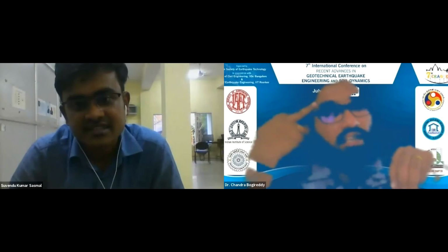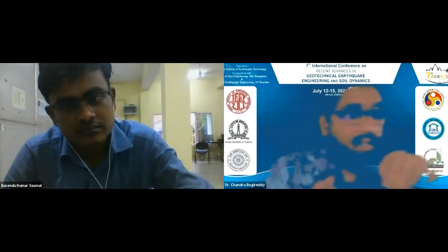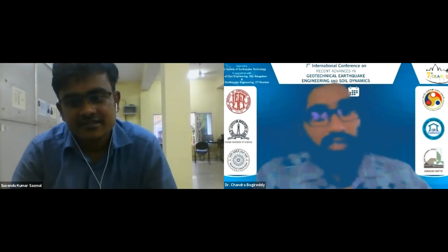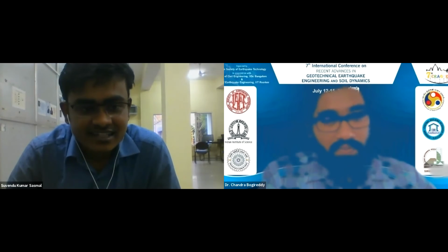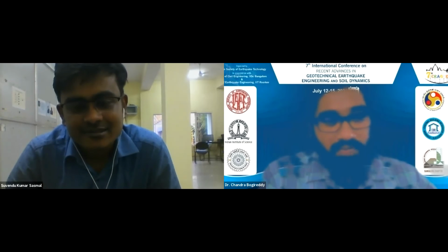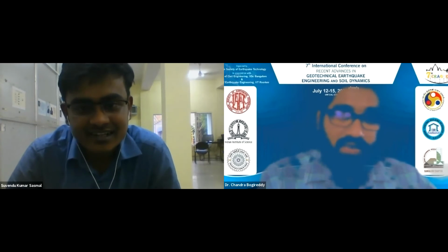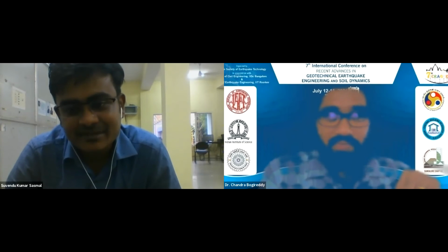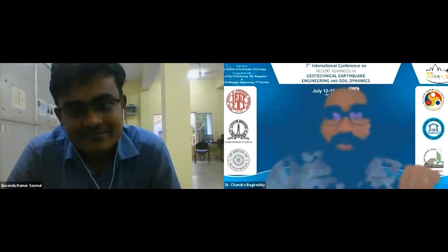Literature. Okay. One more question: why do you want to use the Mohr-Coulomb method to compare the result? Is there any reason behind it? Because in hardening soil methods and HSsmall methods, there are so many assumptions. In this cyclic response study, those assumptions are not accurately done. In the Mohr-Coulomb method, there are fewer assumptions, and it is found that the more the assumptions, the more complicated is the model.